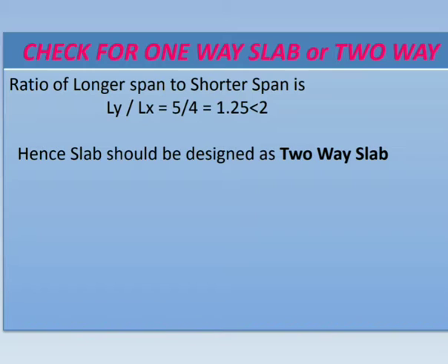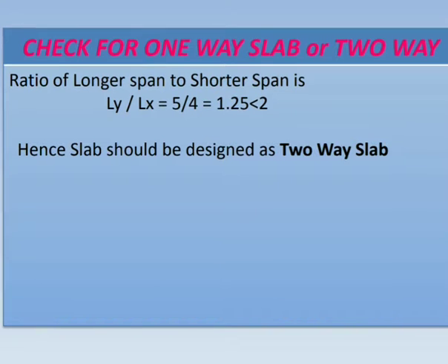So now we have to go for the design of a two-way slab, but the edge conditions are not mentioned clearly. Hence, as I told you earlier, we have to refer to condition number 9 for taking the coefficients alpha x and alpha y. So we have to read the example carefully. As it's a restrained slab but no edge conditions are mentioned, it indicates that you should refer to the ninth condition of IS 456 code, Table 26. Further in the example we'll come across it.